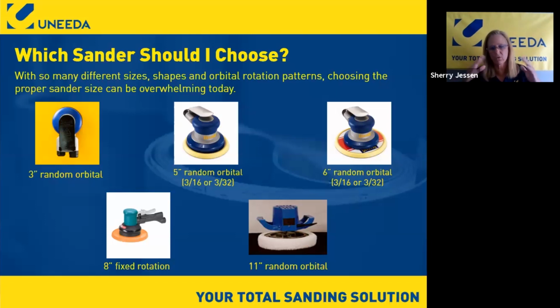You hit a breakthrough, and once you break through, the swirls just appear. It's one of the reasons why, when we're random orbital sanding, we're very careful to make sure that the side of the table is lit up and that we can see what we're sanding. When we feel that the cross grain has been removed, we can stop before we start with the swirls.